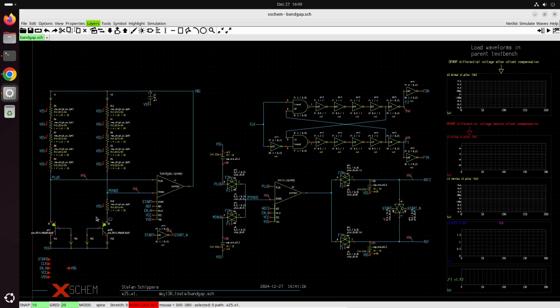We have these bandgap circuits. So we have this BJT, this op-amp making these two points the same, and then we generate PTAT on this resistor, right? So I think I'm going to look at every example circuit here. It's a very good way to start here.